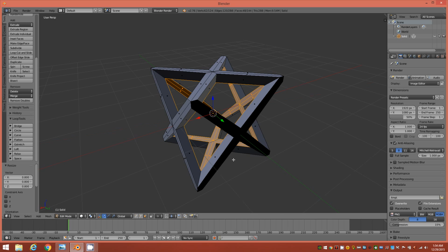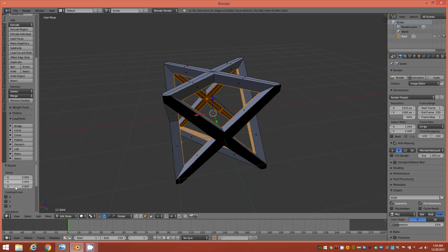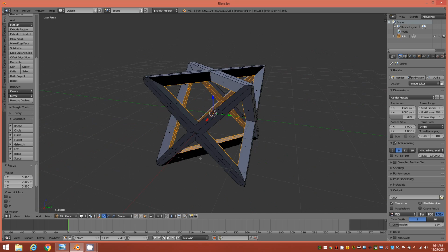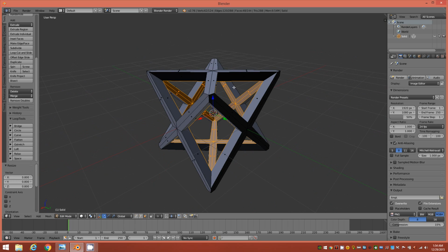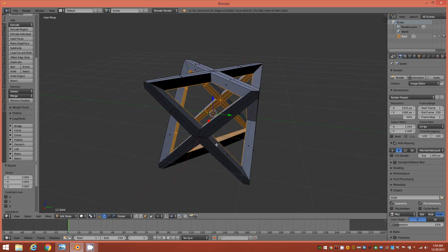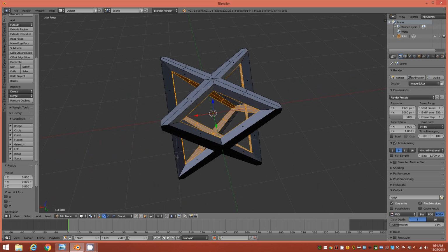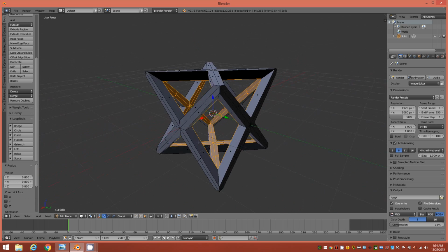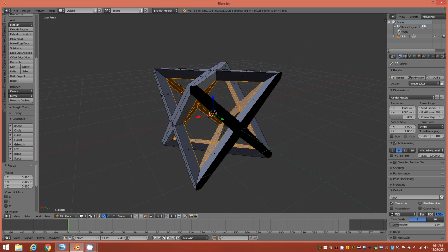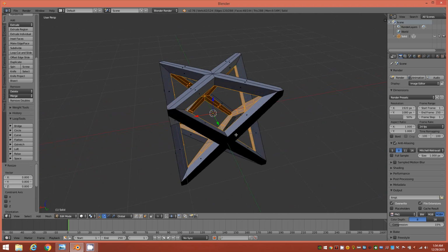As you can see over here on the left hand side, we've scaled down uniformly to 0.8 on the vector XYZ. So 0.8 to the inside, and this way we're not affecting the size of the object that we started with. That's only if you're intending to export this as an STL for 3D printing. You'd want to perhaps maintain the original diameter of the object.